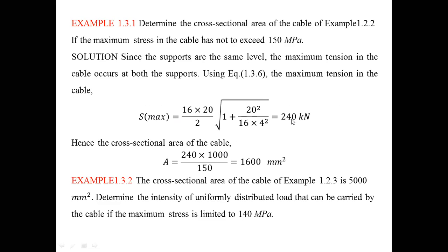This is more. That's why it's S maximum. So the tension in the cable is maximum, 240. Like that you got the maximum stress. So maximum tension divided by stress will give the area.